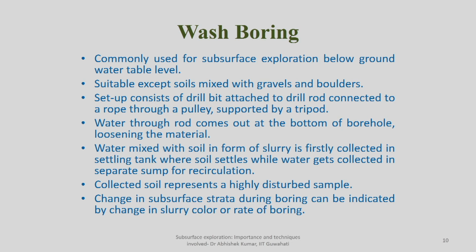Because of this water coming out from the drill rod, it is loosening the soil available at the particular depth. That is why I told you this method can only be used for soil, but it cannot be used for gravels and boulders, because there you require pressure significantly higher than the pressure the water coming out from the drill rod is exerting. So, this way you will be able to scratch the material, and whatever material is loosened at the bottom of the borehole gets mixed up with the water.